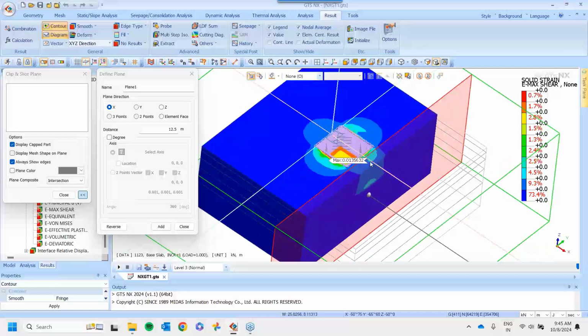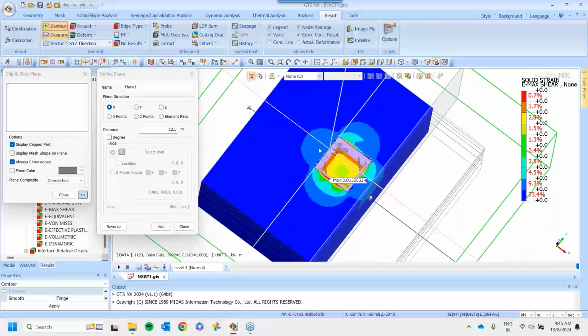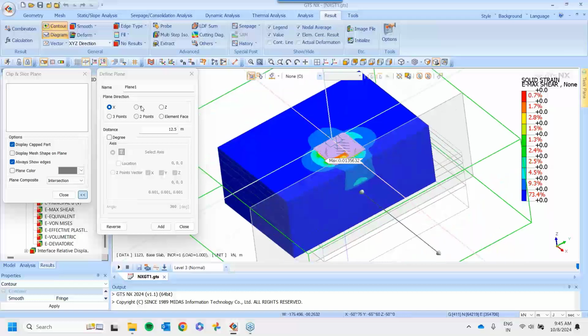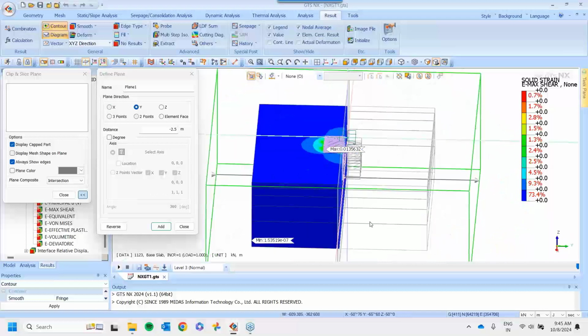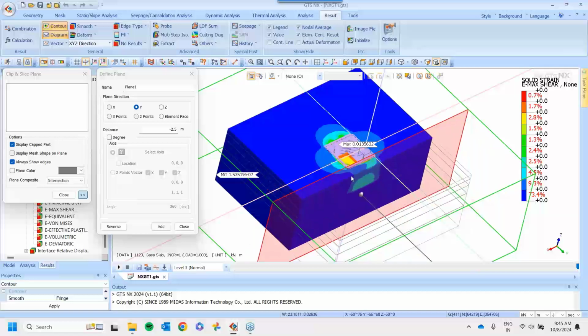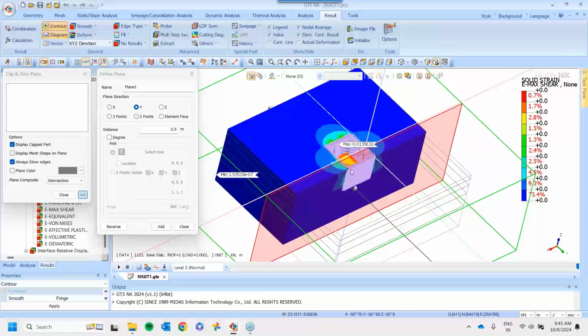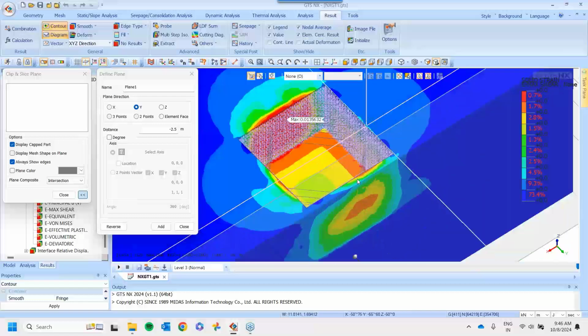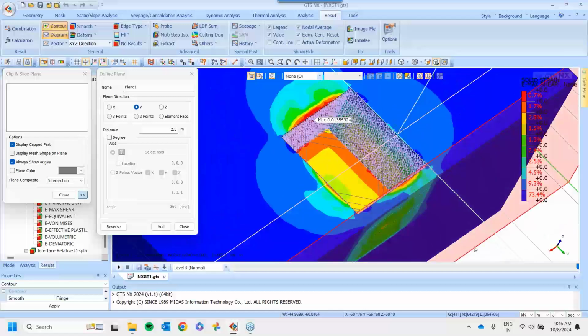and this is the area where the excavation influences the local site, okay, and it can be seen either from the X and also from the Y direction, like this, okay. So the shear zone due to excavation is very close to the vicinity of the excavation, approximately 1 or 1.5 meters. Beyond that, there is not much of a difference.